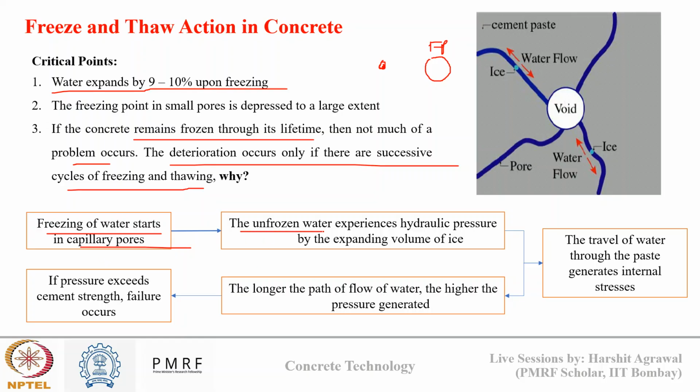Now the unfrozen water, due to this freezing, experiences hydraulic pressure by the expansion of ice. You can see here, suppose there is some ice formation, it will try to expand. Due to this expansion, the unfrozen water will start to experience some pressure. And as it experiences pressure, the water will try to flow. Since the water is in the pore spaces around the cement paste, this movement of water will generate internal stresses on the paste.